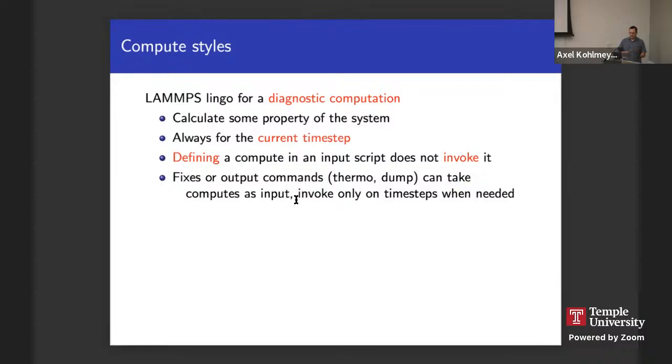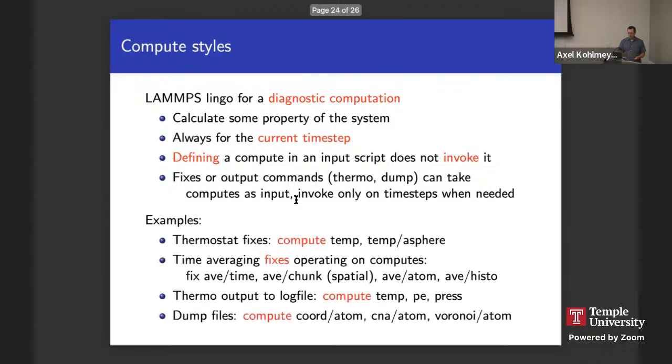So other fixes or output commands are the only things that invoke computes. Like if you have some thermo output or a dump file, then that will actually go and call the compute, and only when needed. So some examples are like a thermostat, like a temperature, compute temp.